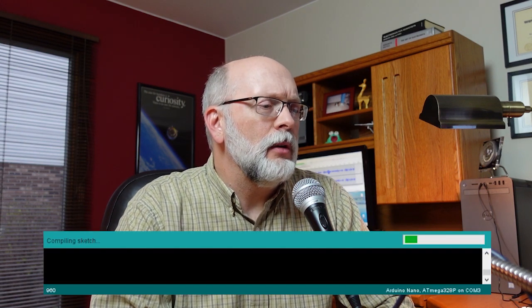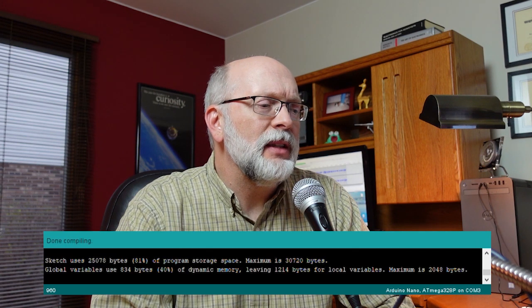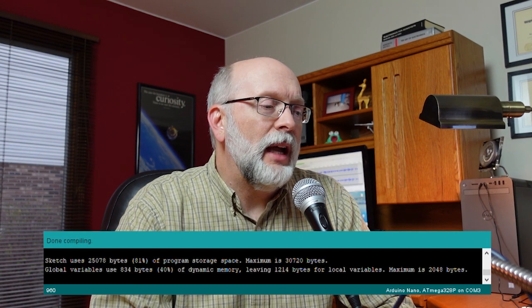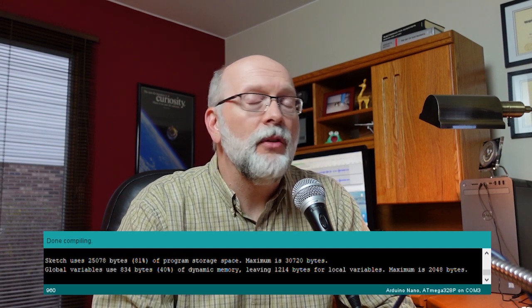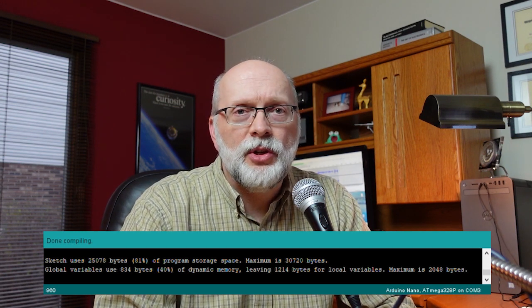I also want to talk about software one last time in the end of this episode. If you remember, I was pretty adamant about wanting to make efficient software and keep the size small. Since I did that video, I added more features, so that generally means the software is going to get bigger. It did a little bit. My final total, according to the Arduino IDE, is 25,078 bytes of the flash consumed and 834 bytes of the RAM reserved. So I ended up with a pretty decent amount of free RAM there. I've been using the receiver and haven't had any issues with it locking up, so I should be fine with that much RAM free.